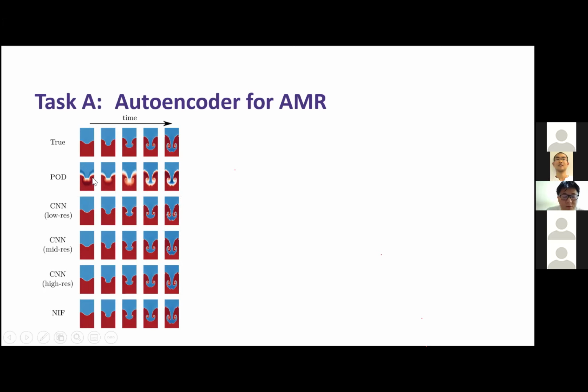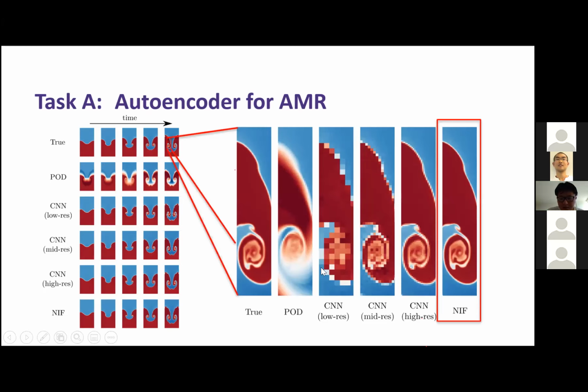If I take rank 2, because I want to visualize the POD much better, as you can see, the POD at the same number of ranks, using the same rank 2 as any other frameworks, is sort of blurry around the front of these material interfaces, which is not really pleasant. However, for CNNs, if we take a closer look, we found that the CNN really requires pre-processing, and that pre-processing really determines the quality of your